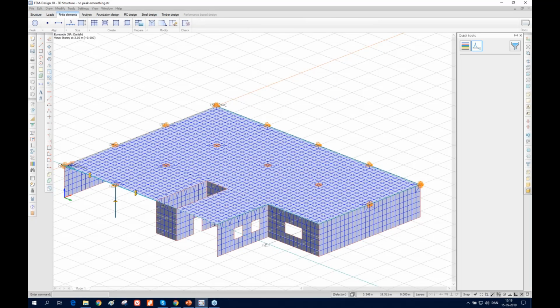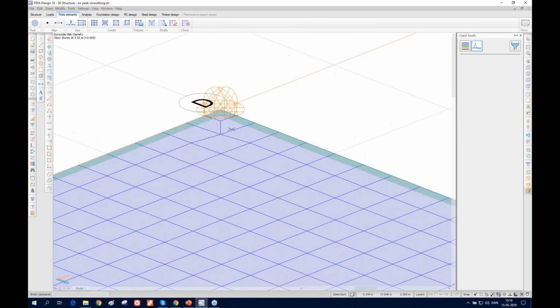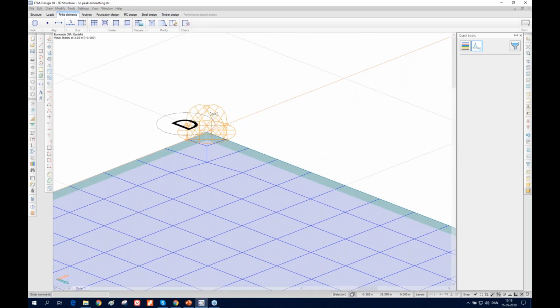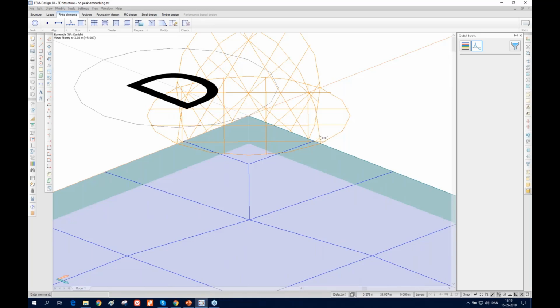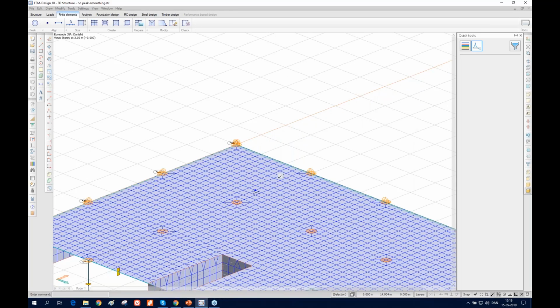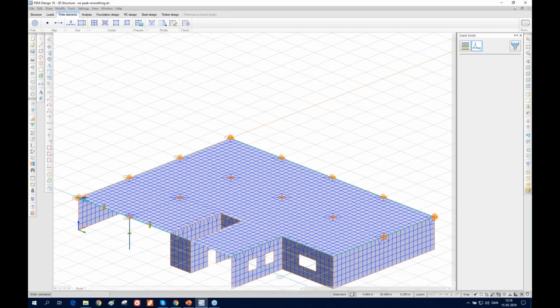Previously, if you applied peak smoothing, the mesh automatically changed, and FEM-Design created fine mesh around the area of the peak smoothing. This generated a lot of mesh problems, especially in cases like this where they overlap each other, generating fine mesh in the area where they overlap or cross. That's why we have improved it, and now they are independent from each other.